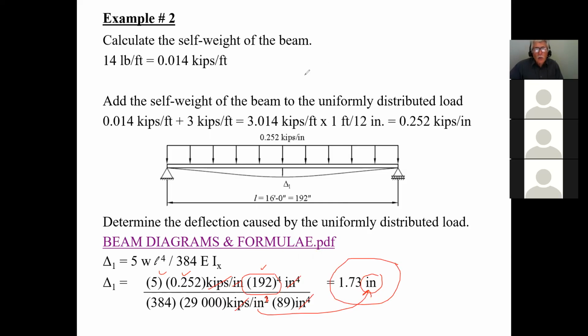Oh yes, guys, when you're doing things in metric and calculating deflections, please, one decimal place is ample. I mean, 0.1 of a millimeter or 0.7 of a millimeter, that is ample for precision. And when you're doing it in inches, two decimal places is ample. Don't go to 3, don't go to 4. That is accurate enough for deflection. So do yourself a favor. Do not bring this to 3 or 4 decimal places. Especially in metric, one decimal place is ample, imperial two decimal places is ample, and that's all you need to do.